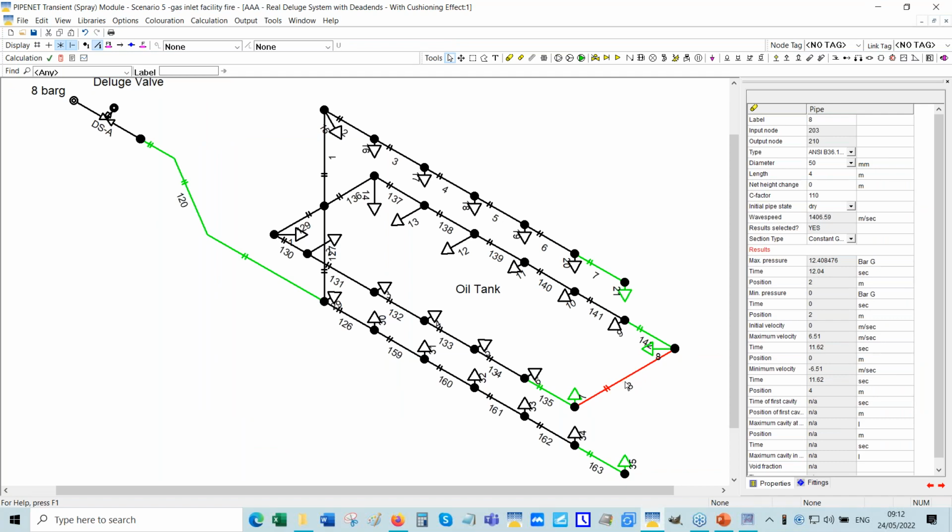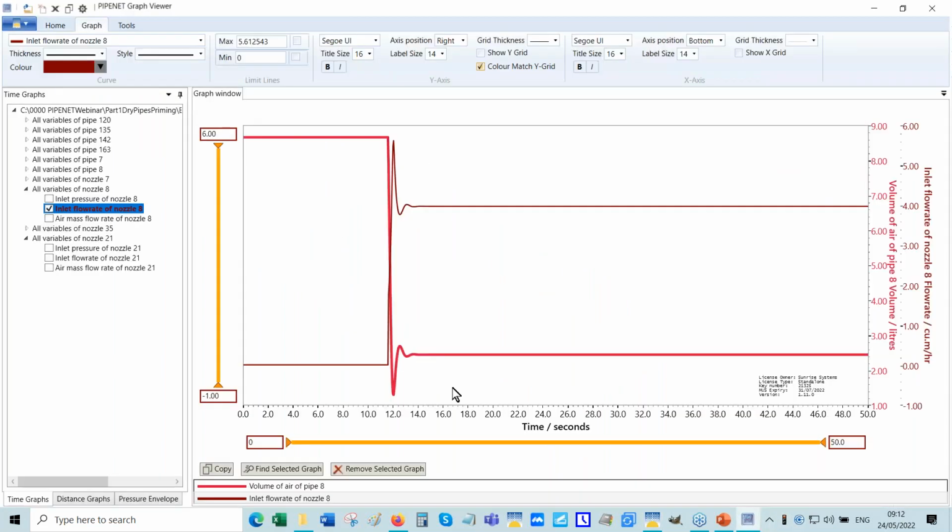It will actually change the volume. And as you can see, the volume will oscillate slightly, and the flow rate through the nozzle will also oscillate in response to this. This is why when you open the tap in your kitchen, sometimes you have this kind of gulping effect, and it's because of things like this. It'll be worse if there is some air trapped in the system. Okay, and mathematics is so beautiful that it can predict all of that.